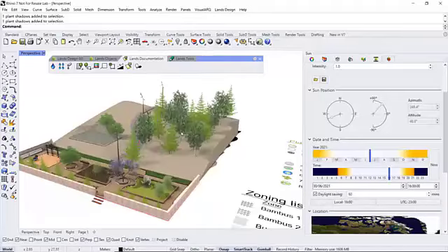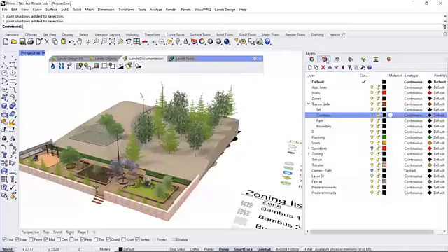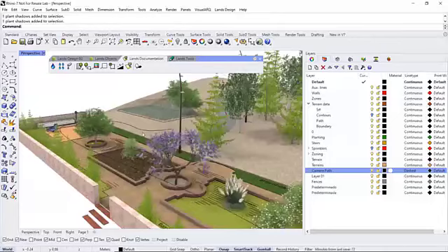All right, maybe it's the moment to play an animation. So I'm going to move to the Land Animation panel, and notice here that we've got this camera, and we need to define a path. I've got a specific layer with a curve that I'm going to use for the camera path.